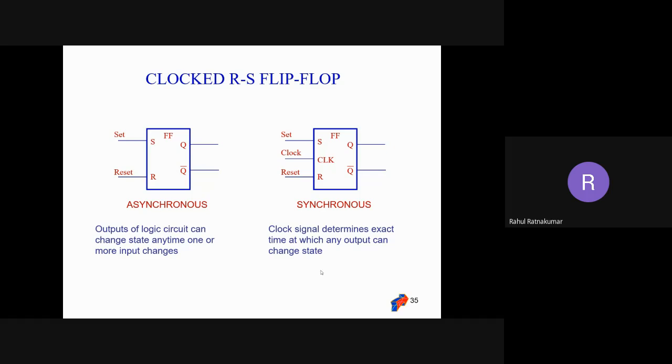Asynchronous circuits can also be sequential. There's nothing stopping sequential and combinational circuits from being asynchronous, but there will not be a synchronizing signal, right? Say there are two modules, A and B, trying to communicate with each other. A sends a start signal, and B replies, yes, you can start. Then A starts sending signals to B. So this is a handshaking signal. We don't have a clock, right?